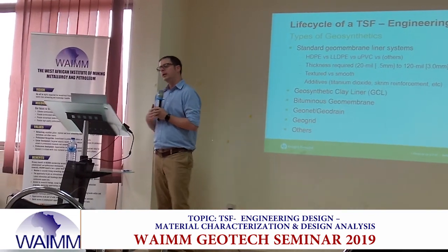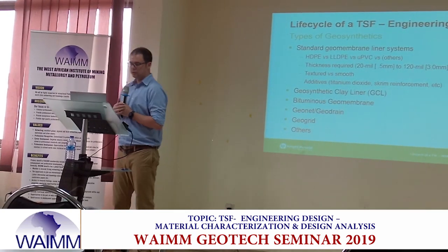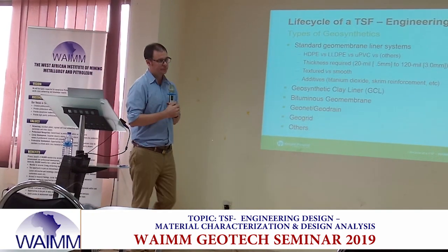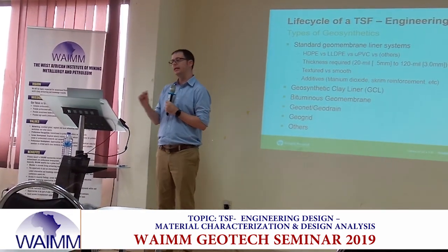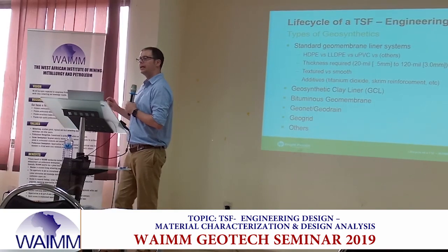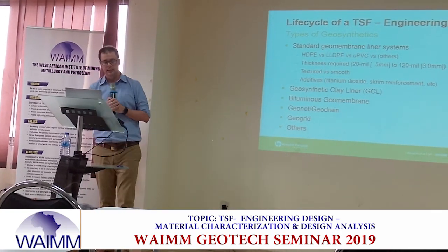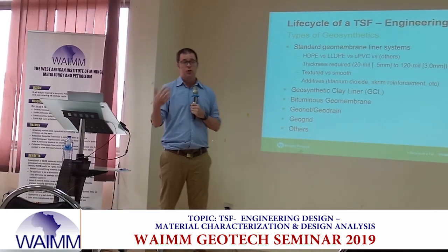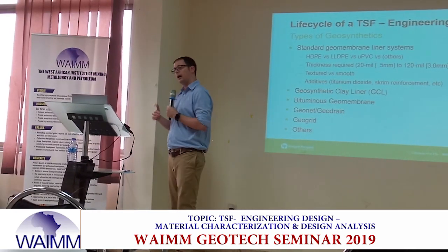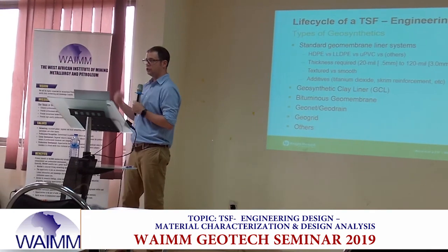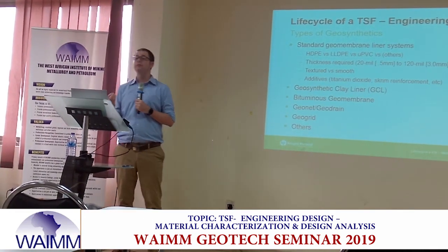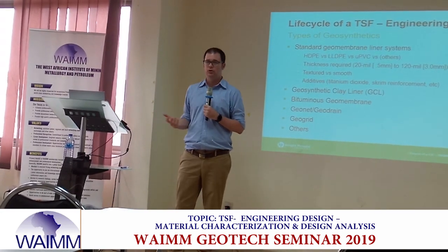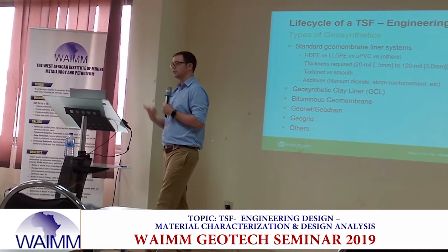Beyond pure geosynthetic products, we also have things like GCL, geosynthetic clay liner, which is a fabric with bentonite in between. And so that bentonite has very little hydraulic conductivity. The benefits to it are the hydraulic conductivity. The risks are, if you don't confine it very quickly, as soon as it hydrates, it becomes very, very weak. And once it becomes weak, there's nothing you can do to fix it. It just sloughs off and slides down.